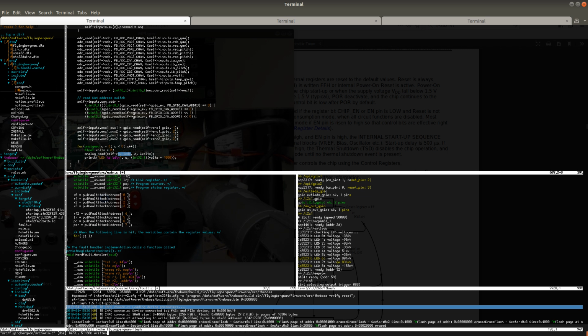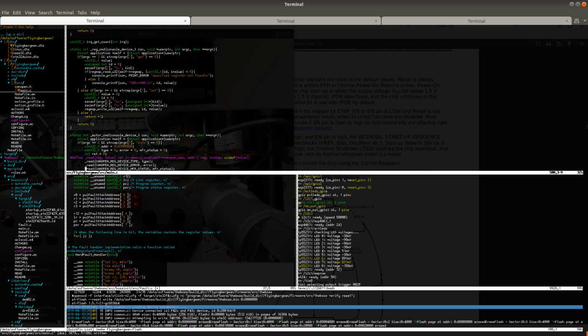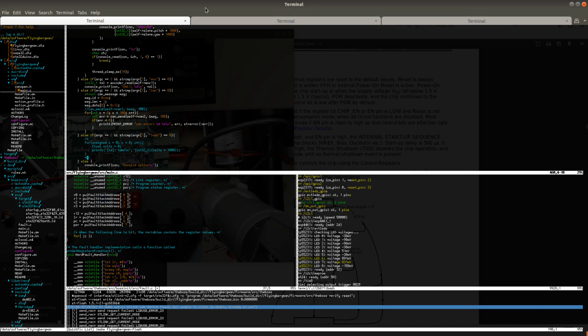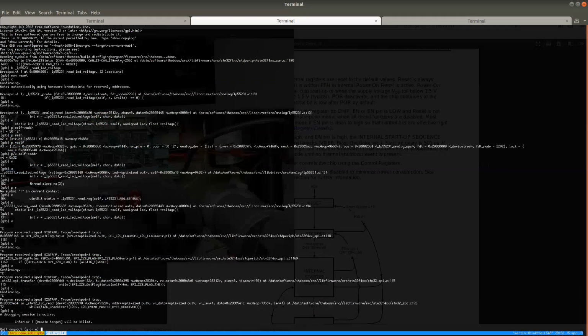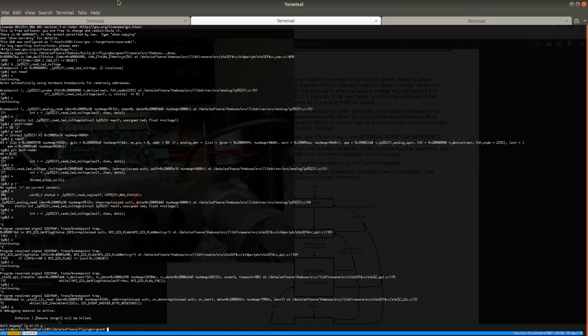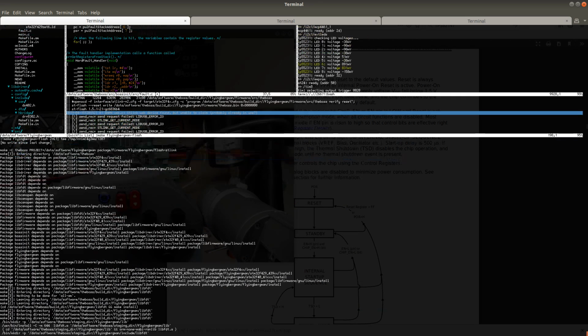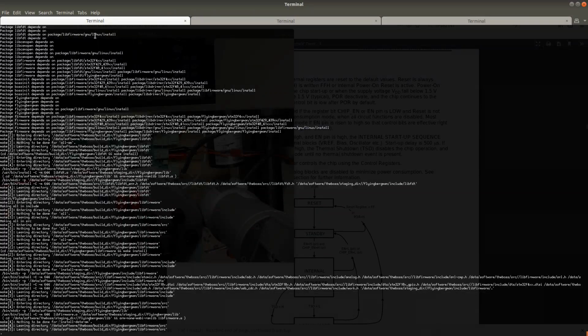This will actually just print continuously, and I'll just remove this text here. But the difference is that now it will be doing it as part of the main loop. Maybe there is some interference between the SPI, I2S and I2C.